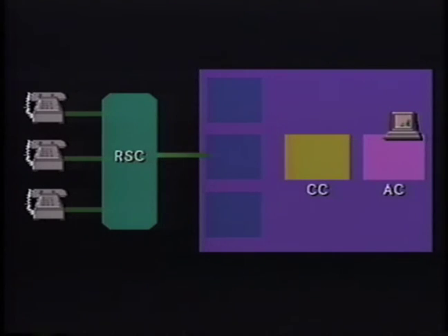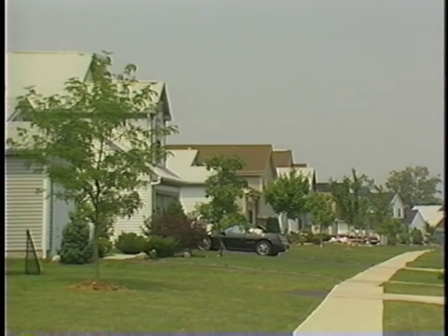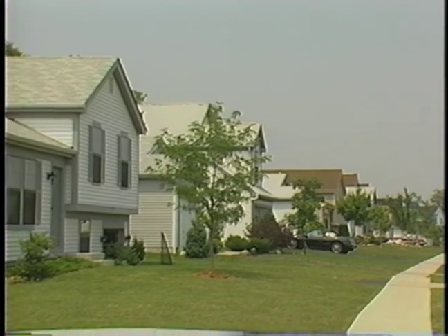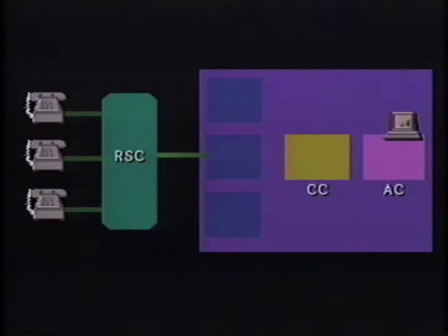With the distributed processing, a switching component can operate from a remote location. This remote switching component serves newly installed lines in an outlying area served by the central office. Calls between these lines can be switched directly by the remote switching component. The remote site is connected to the rest of the system through a host switching component located in the central office. Through this connection, information from the remote site is transferred to the communications and administrative components.